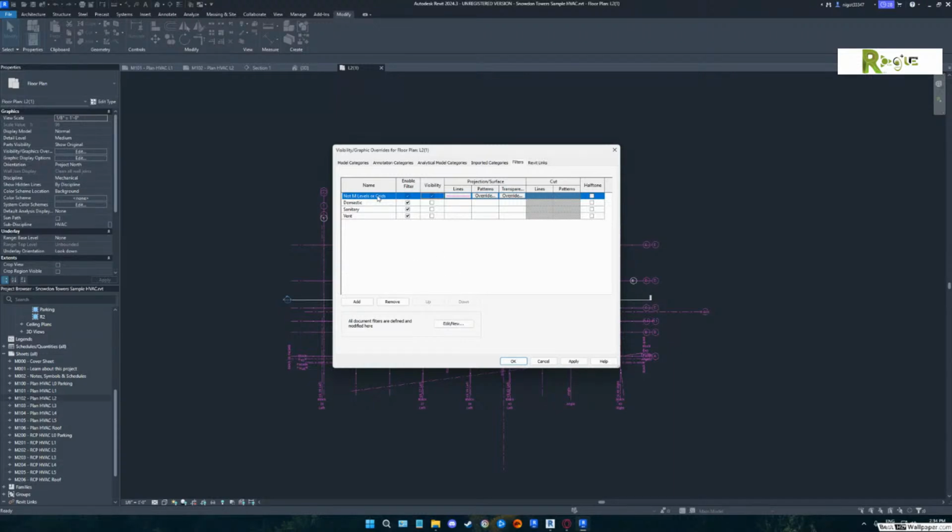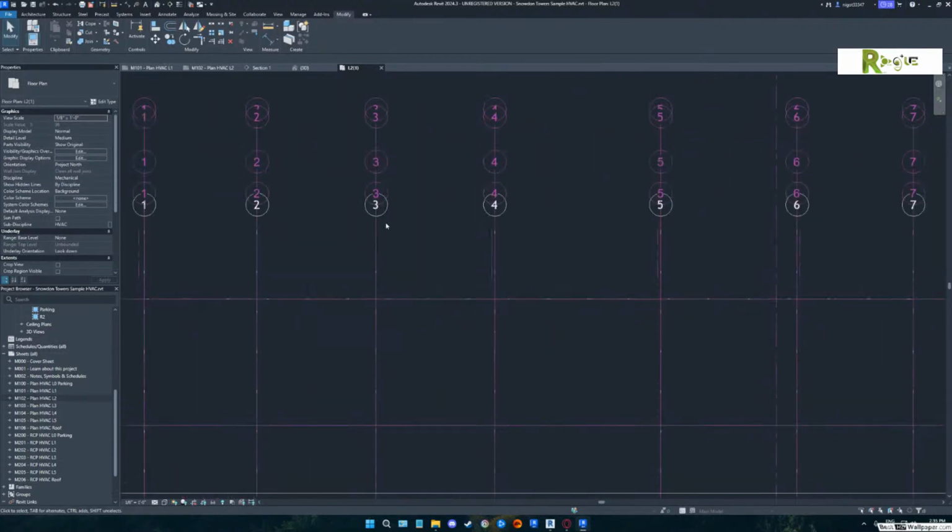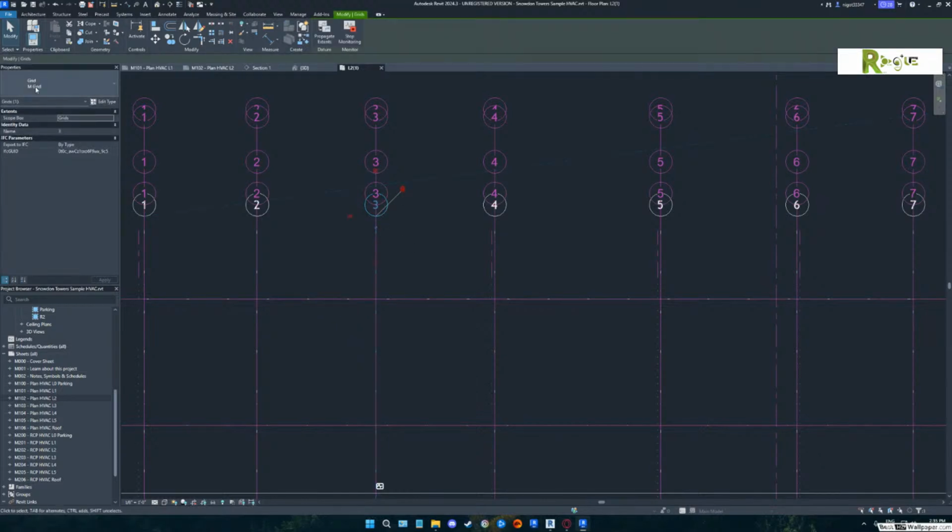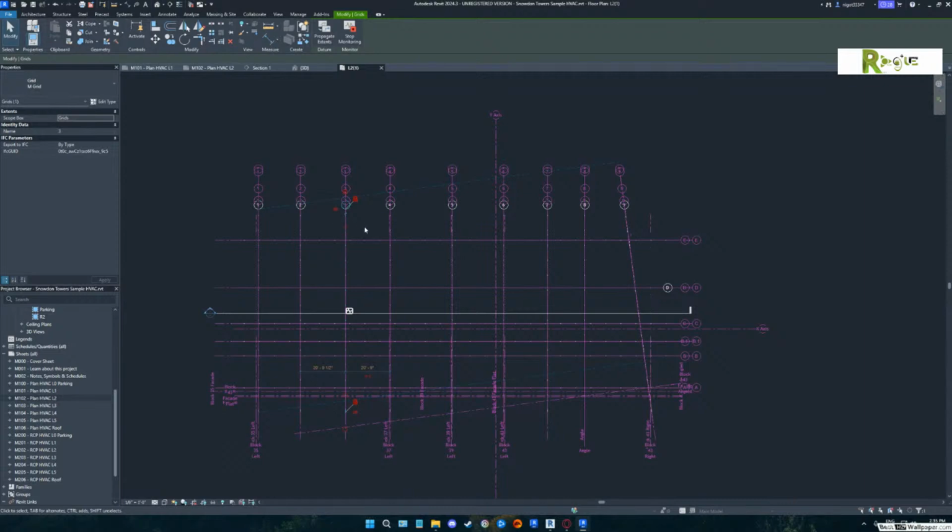And then that filter, you can actually copy that filter from this file to your plumbing file. And what you do is you name your grids, plumbing grids, your grids, HVAC grids, your grids, architectural grids, your grids, structural grids, then your filters still work. So if you hit cancel and you pick one of those white grids, what is its name? I'm guessing it's named M column, M grid. So they tried to do what I was doing, except they only selected one of their level lines. That was what happened. Mm-hmm.